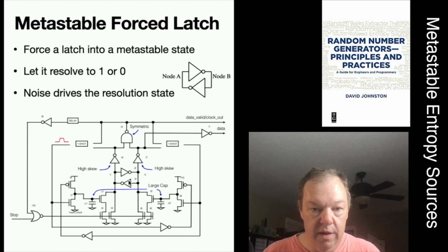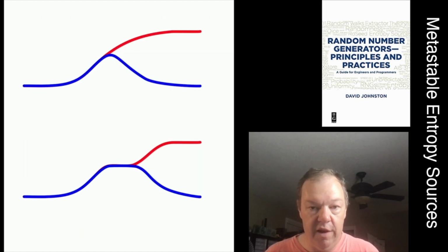what we'll see is, let me go to this diagram here. When a circuit goes metastable in silicon, now it's possible to have metastability where the state of it is flip-flopping between a 1 and a 0 until it decides to go one way or the other. That's not what happens in silicon. You get some current through both legs of the circuit, and it kind of hangs around in the middle until some noise kicks it to go one way or the other.